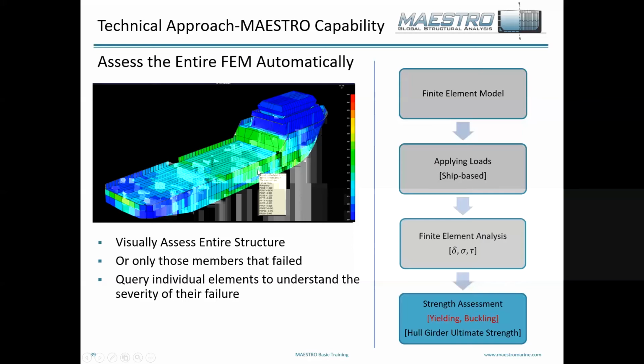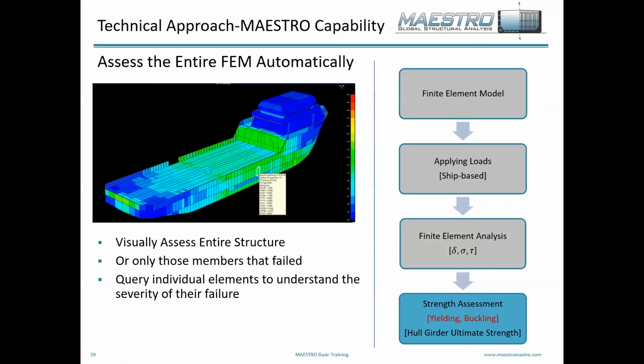And as we mentioned earlier with the dynamic query, you can, in this case, rather than recovering stresses, recover what are referred to in Maestro as adequacy parameters, and it non-dimensionalizes the results from a scale of -1 to 1, since if something fails, you could have values going up to infinity.